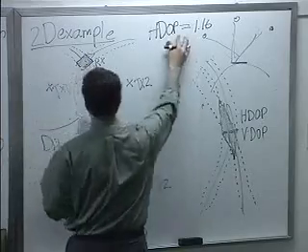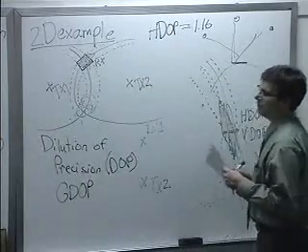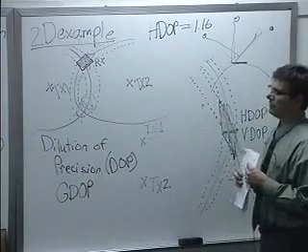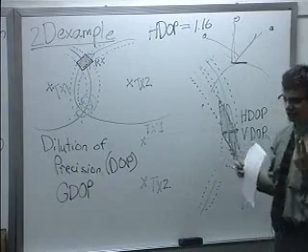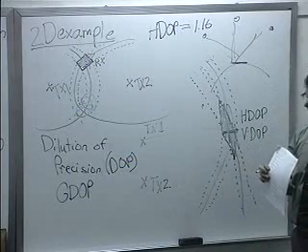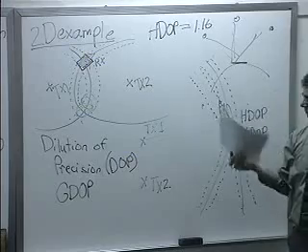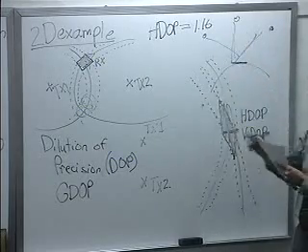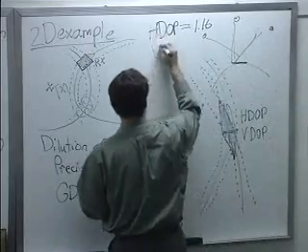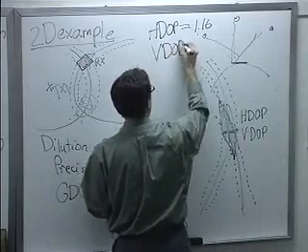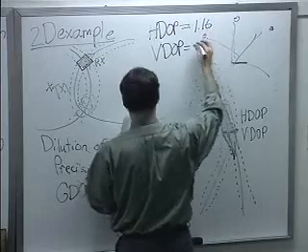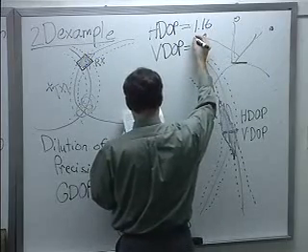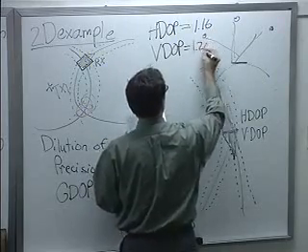You multiply that by the error estimate that we put over there on the board, and that gives you the true error estimate of GPS for a typical dilution of precision error if your satellites are not ideally spread apart. VDOP is a little bit higher. GPS doesn't do quite as well with vertical ranging. That's going to be 1.26.